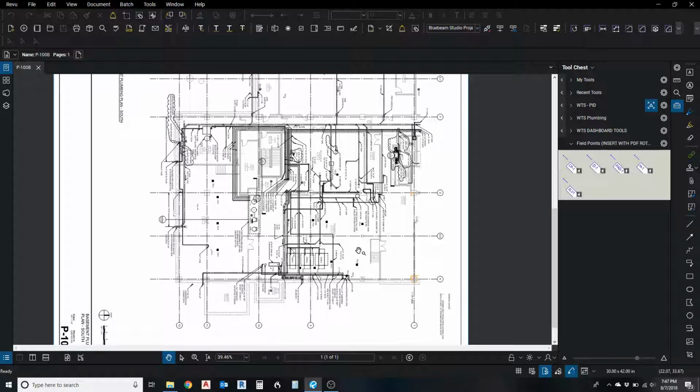All right? So when we're doing layout, we're intending this layout to be in areas that are a couple hundred feet by a couple hundred feet. Don't lay out an entire building like this. I mean, you can, but you need to be very conscious of control at that point. So don't do that until you're an advanced user. Once you're an advanced user and understand how all the coordinate system works, no problem. You can do that all day.